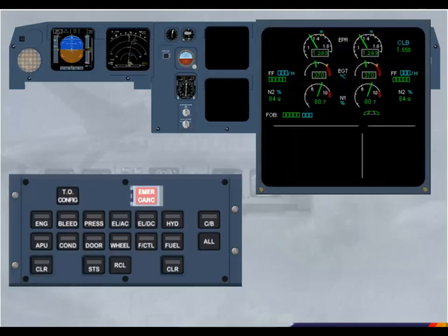When you are limited to a single ECAM screen, the handling of system malfunctions and how you are advised of failures is slightly different. For clarity, we will concentrate on the ECAM screen. If an advisory condition arises, the relevant system page is not automatically displayed. Instead, the light on the push-button switch for the system and a boxed advisory message on the engine warning display will pulse.